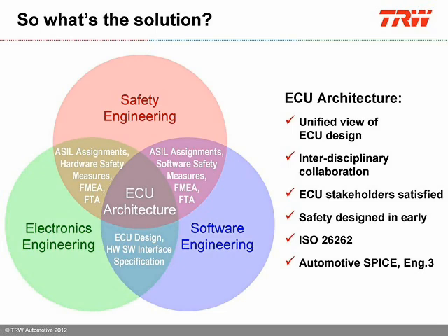It considers the impact of safety up front and enables us to address the needs of ISO 26262 and Automotive SPICE. The approach aims to capture what is in people's heads, such as goals or concepts, by defining those thoughts using the language of SysML. This enables multiple people to have a common understanding. By integrating the ECU architectural work of all the engineering disciplines into a common point of reference, we can ensure that the ECU architecture provides a unified view that addresses the demands of all the engineering disciplines. The overall key benefit of this approach is the structured collaboration between hardware, software and safety disciplines.